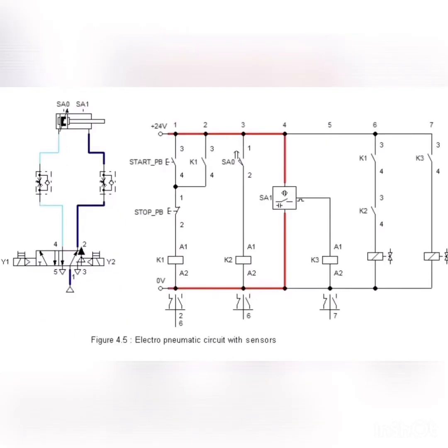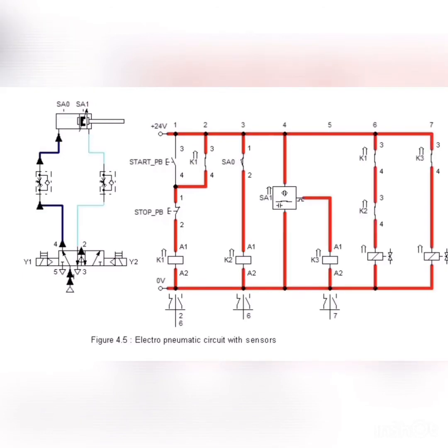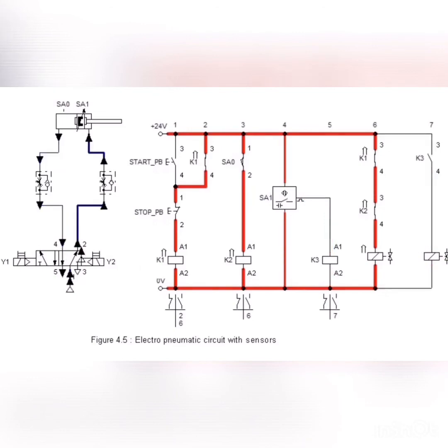When start PB is pressed, the valve block will change from right to left continuously and this makes the cylinder change its position, extend and retract continuously. This happens because there is no holding circuit in this simulation and the actuator will keep switching from right to left continuously.